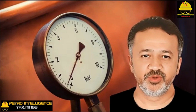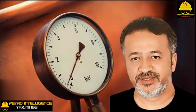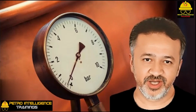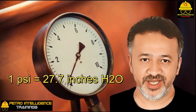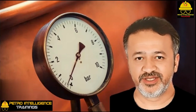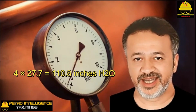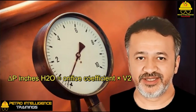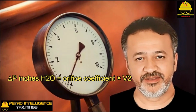Suppose the flowing fluid is water. Assume the area of the orifice is 0.1 square feet. The observed delta P equals 4 psi. Converting psi to inches of water, 1 psi equals 27.7 inches H2O. Therefore, the observed delta P expressed as inches H2O is 4 times 27.7, which is equal to 110.8 inches H2O. The linear flow rate, V, in feet per second is found from delta P inches H2O equals orifice coefficient times V squared.